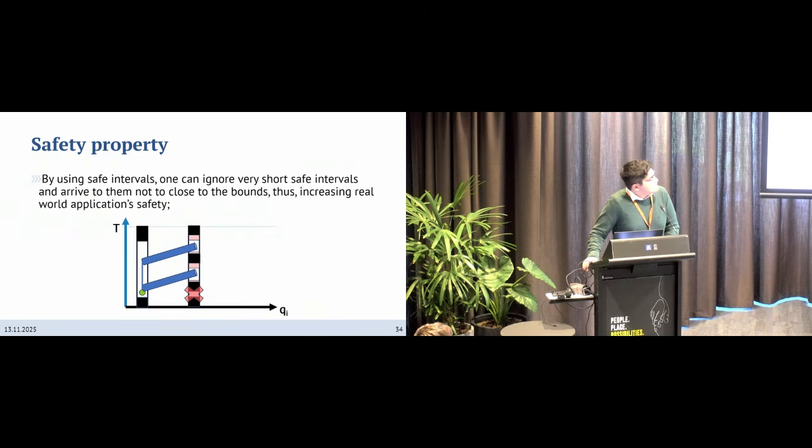Also, we found a safety property of our algorithm. Because we know the time periods when it's safe to stay at the configuration, we can ignore really small time periods, and we can constrain the arrival and departure time from the safe interval, thus increasing real world application safety.